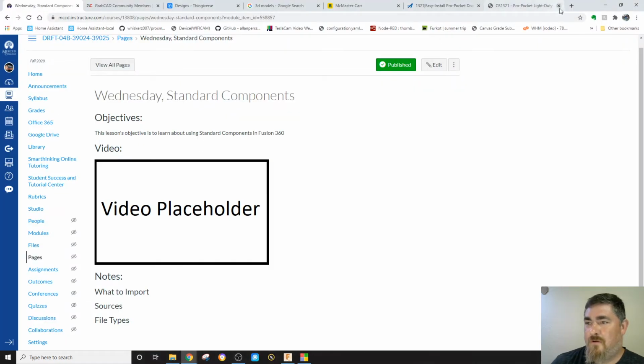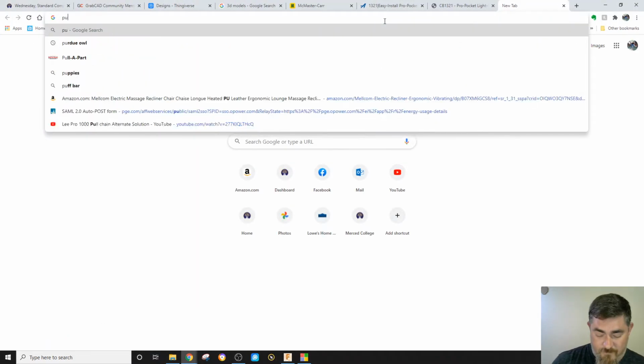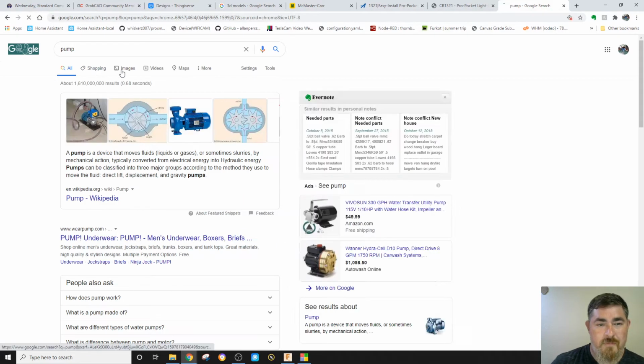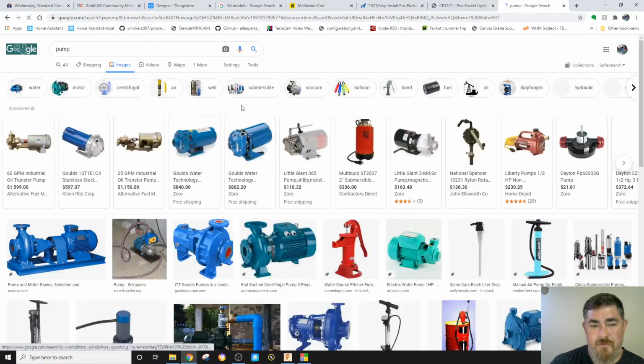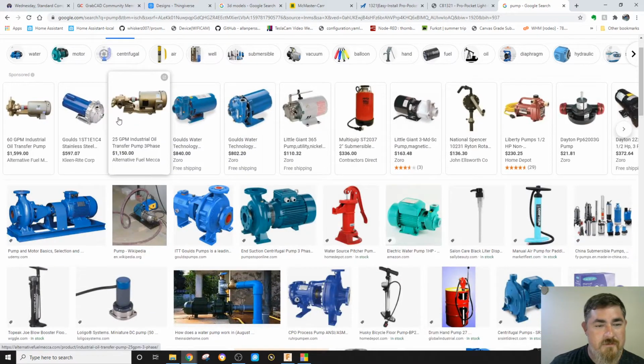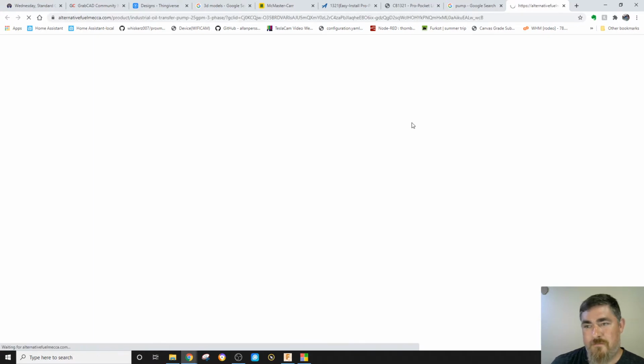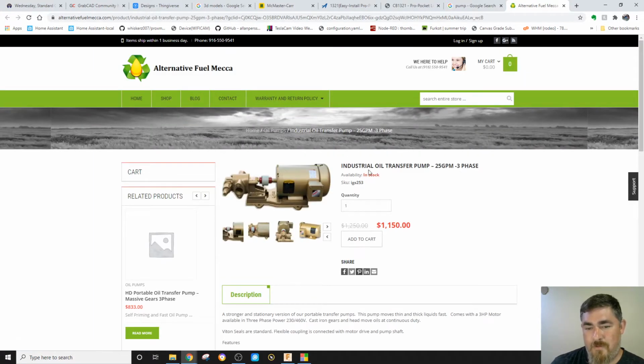So let's pull up an image of a pump. Let's say we're going to use this pump here in our design. What would we need? Well, these mounting holes down here, we'd have to know where those are pretty precisely. We'd have to know where this mounting thing is for this connection, both the size of this hole here and where those two bolts are and their sizes. We need to know those things precisely.